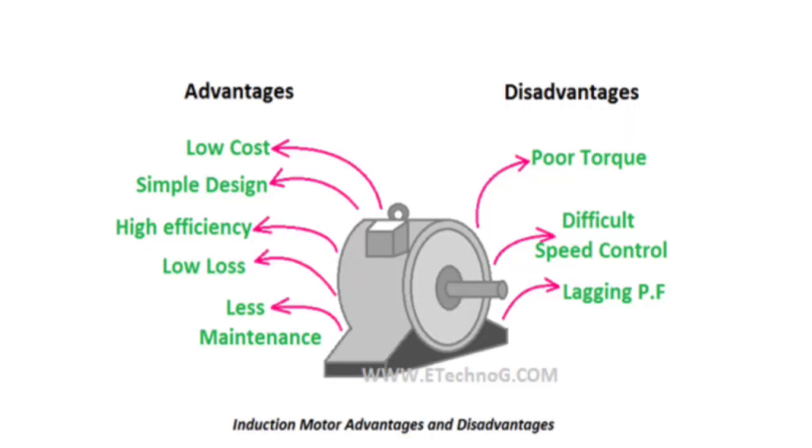Next, advantages and disadvantages of induction motor. The induction motor has low cost, simple design, high efficiency, low loss, and less maintenance. In the same way, we have some disadvantages: poor torque, difficult speed control, and lagging power factor. These are the advantages and disadvantages of the induction motor.